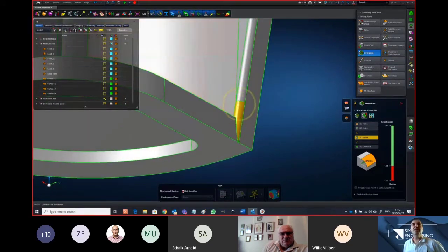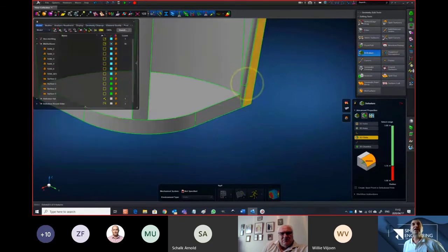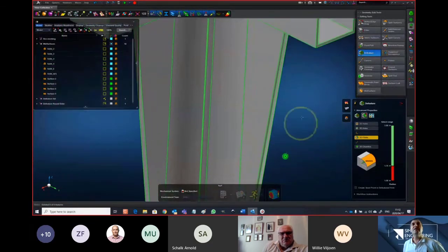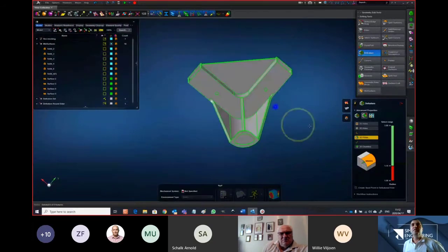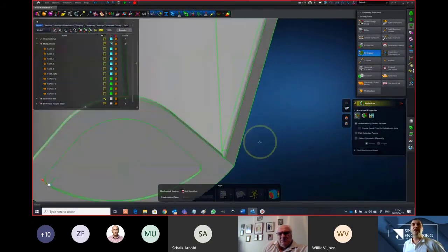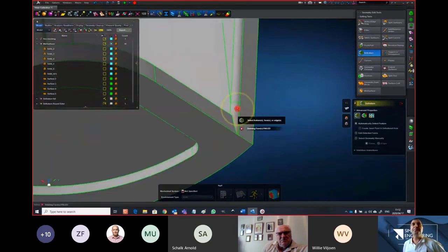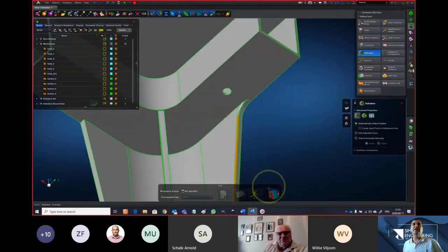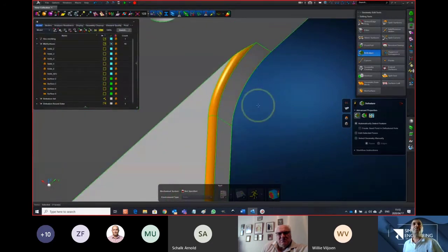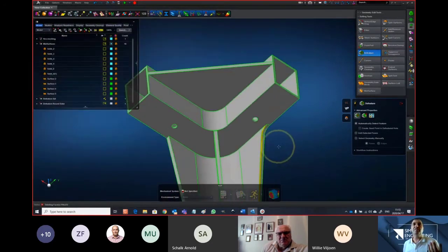As you can see over here, there's a range of fillets. Although they were included in the selection, it did not defeature. The next logical step is to try and defeature them manually, and even press Alt and double click to select them, or switch the automatic one off. Now that obviously is not going to help. So let me select these manually. And again, I see I can't get rid of this feature.